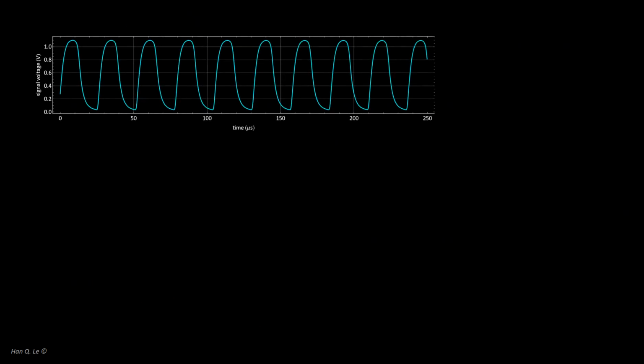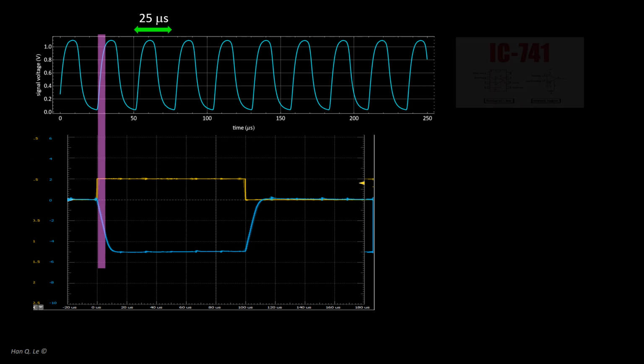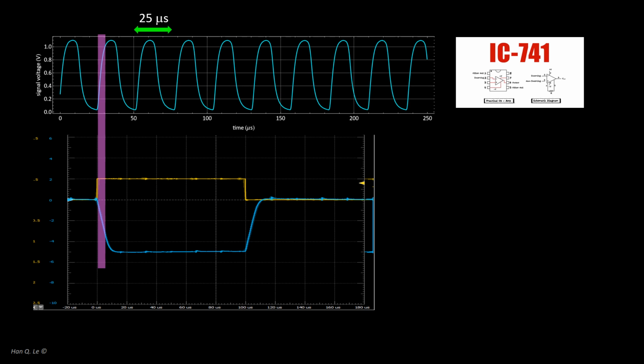Likewise with the frequency domain analysis, we can take a close-up look of the remote control signal with the time domain perspective. The top graph is a fine time scale plot of the signal with 10 dB gain. The bottom graph is the Heaviside step function response done in Part A. Notice the comparable response time. In fact, the response time in the remote control signal should be even slower than that of the signal of Part A, because the optical receiver signal went through two 741 op-amps, and its time response is a convolution of both, which is a tad slower than the single op-amp voltage amplifier response in the bottom graph.